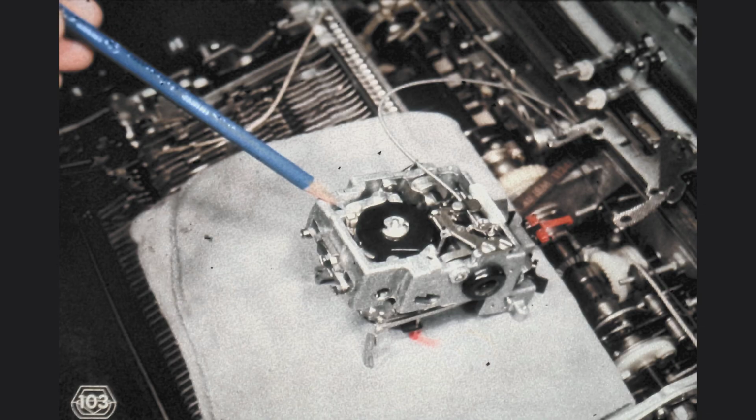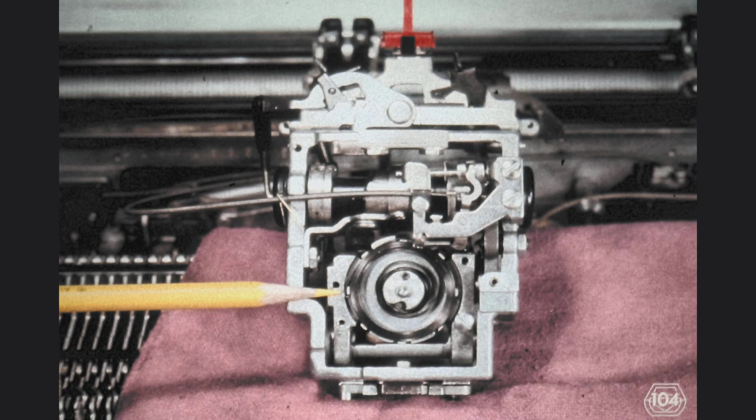Let us also remove the plate which covers the spring cage. It is now possible to remove the spring and its cage entirely from the rocker. Before you remove the spring, notice that the outside end of the rotate spring is located at approximately the 9 o'clock position in this picture. We should be aware of this fact and retain this position if we want to have the exact same 3.5 turns of spring tension at the end of the reassembly process. This, however, is not at all critical because we can adjust the spring tension once the whole mechanism is assembled.